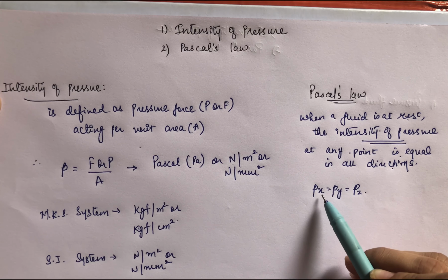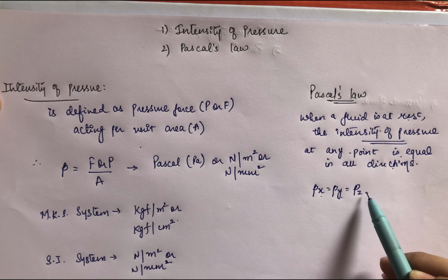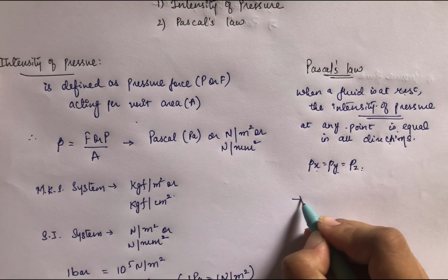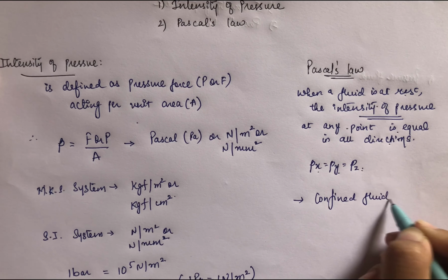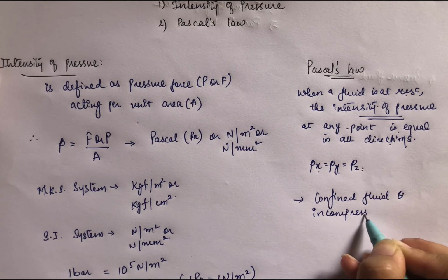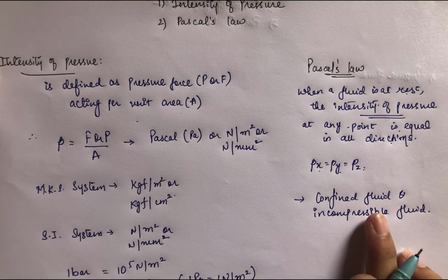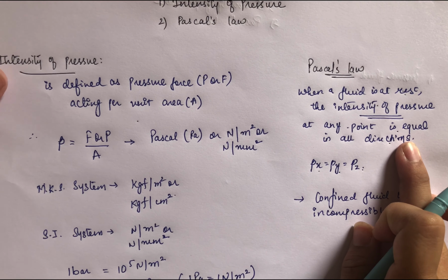That is, the intensity of pressure will be equal in x direction as well as y direction and as well as z direction. One more thing you need to note over here is that it is applicable to confined fluid and incompressible fluid. Okay, so this Pascal's law is applied to confined fluid and incompressible fluid when your fluid is at rest,